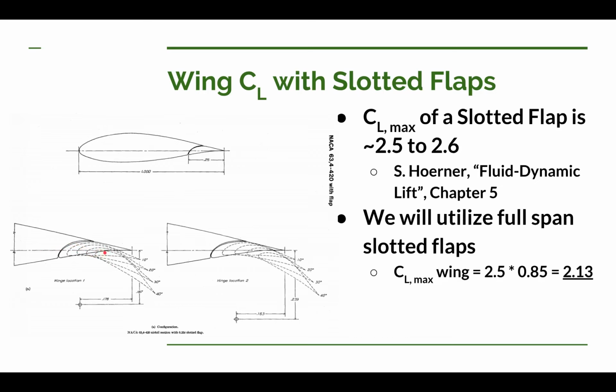So we'll probably have a little something that sticks off the front of this nose, and we'll have a curved slot with a roller for that extension on the nose to roll in. That will at least give support here at the nose. It would not support the trailing edge. So what we may have to do then is just design the flap to be stiff enough so that the trailing edge will not bow out. That's something we'll have to do a little bit of analysis on.